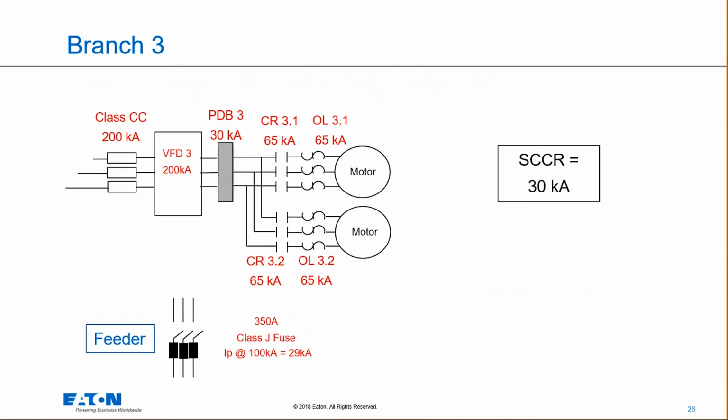As we look, obviously the feeder circuit's letting through less than 30,000. So once again, we could take this whole circuit that was rated at 30,000 and get it over that 65K threshold that we really want to get beyond. We're able to raise the rating using the rules set in place for the feeder circuit overcurrent device.